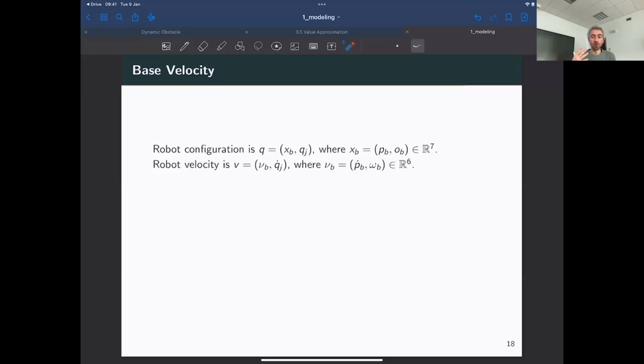One of the key challenges of working with these redundant representations for the orientation is that right now the configuration vector and the velocity vector don't have the same size anymore. The configuration vector is 1 element longer than the velocity vector. That was not the case with robot manipulators. It takes a little bit of mental effort to adapt to this, especially when you're coding.